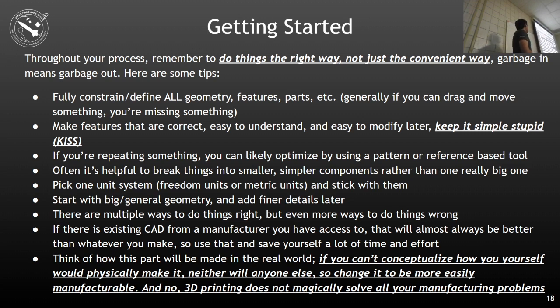But if you're trying to do things kind of janky, where you have one feature and then there's one part of that feature that you don't like, and so you take away some part, like you're cutting away part of a corner or something weird, then you add something back a little bit later. Just make the feature right the first time rather than adding the equivalent of duct tape and bandaging the thing together to get it back to the normal shape that you want. So make sure you just do it right the first time as best as you can.